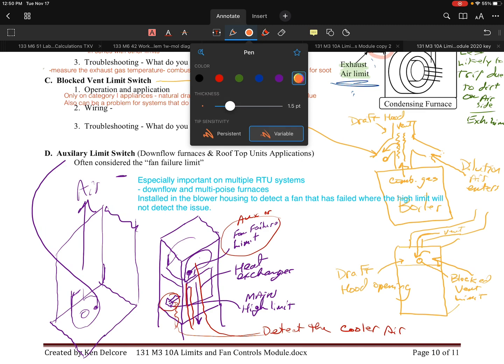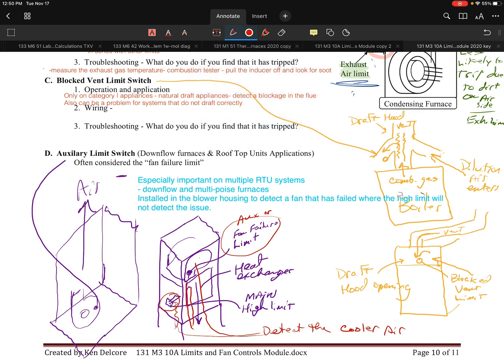But the obvious thing is you've got combustion gases that potentially are flowing up through that appliance and spilling out. They'll go right back into the room, depending on where that is. So that is their access into the room, through the relief, the draft hood or the barometric relief opening. So that's kind of what they're banking on. So you have to really watch that if you run into an issue on a job where that's happening.